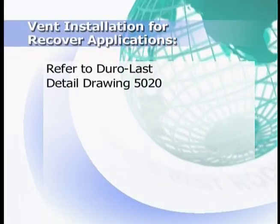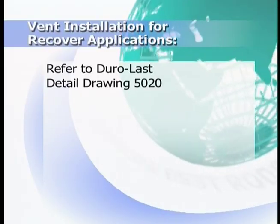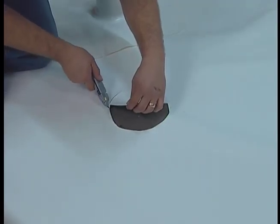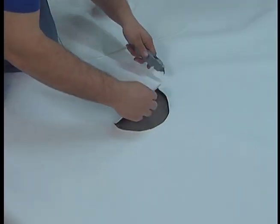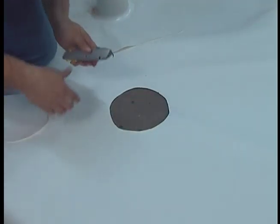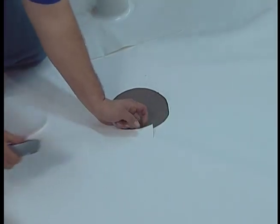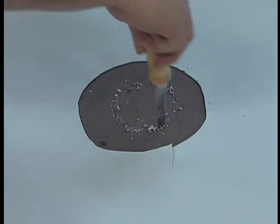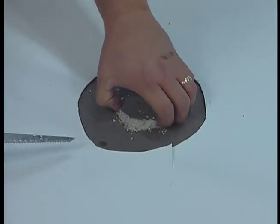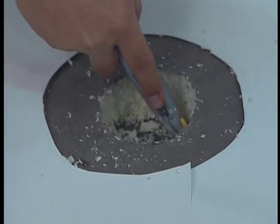Now, let's look at the correct vent installation technique for recover applications. Refer to Duro-Last detail drawing number 5020. Begin by cutting the same 7-inch diameter circular hole in the Duro-Last membrane, making a 2-inch cut from the edge of the 7-inch hole. You've now exposed the slip sheet, underlayment, or insulation below the roof membrane. Cut a 4-inch diameter hole through the underlayment and original roof membrane to expose the original insulation. If a built-up roof is present, cutting through the buildup is not required.